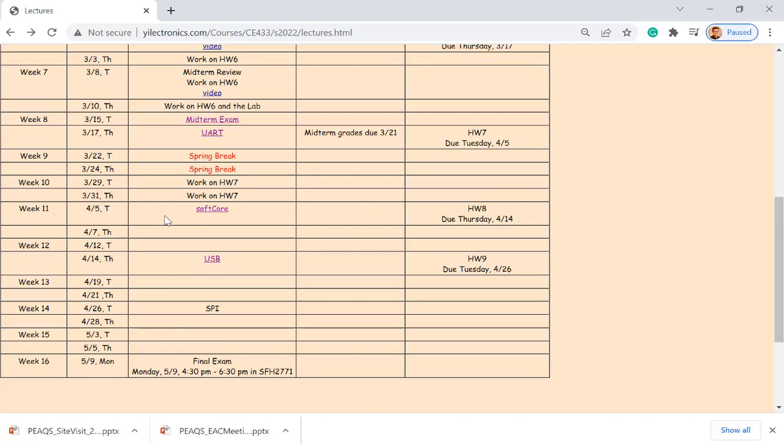You can instantiate it in your Vivado design environment, and you can compile your assembly code and put it into the ROM and synthesize the ROM with your CPU at the same time. So it's eventually going to give you a design to implement on the FPGA. So what is that final product?